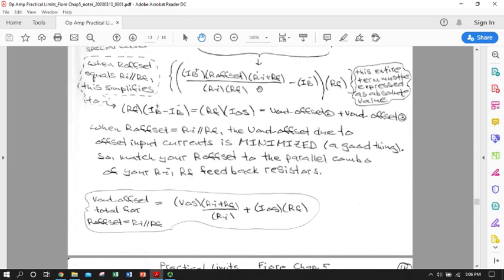And for our purposes, that absolute value will not be in our favor, because what that means is any kind of DC offset error that shows up at our output coming from the current sources can only add to the error that's coming from our VOS. So errors can't subtract from one another other than within this term. So the IB errors can only add to the VOS errors.